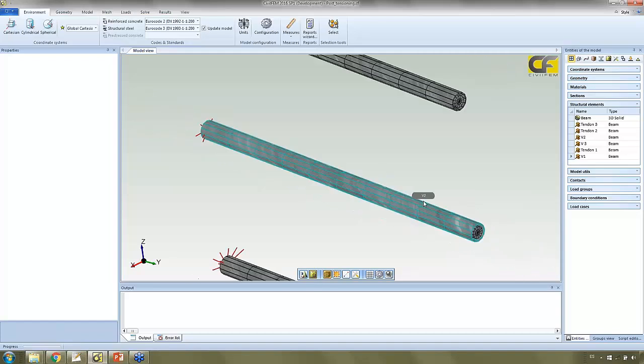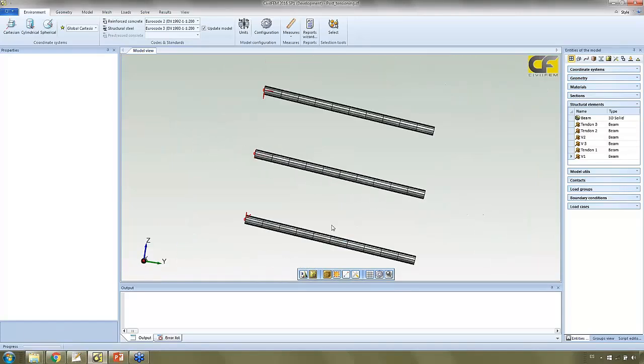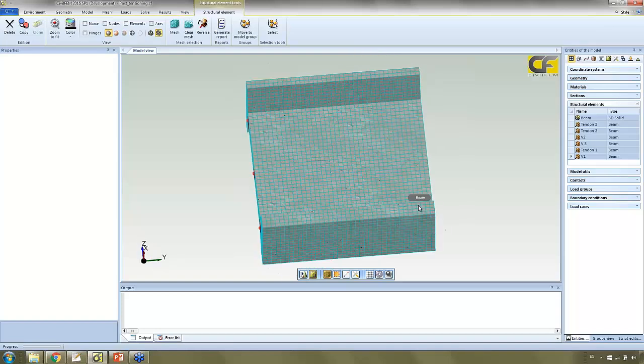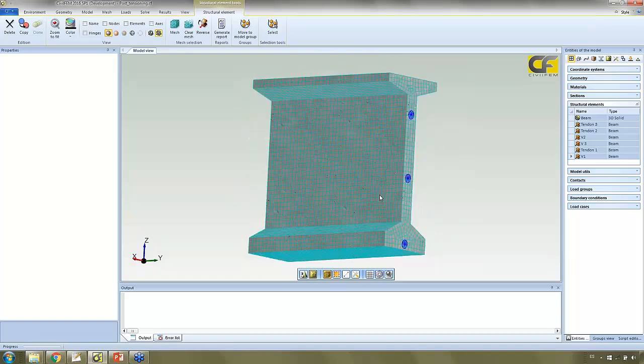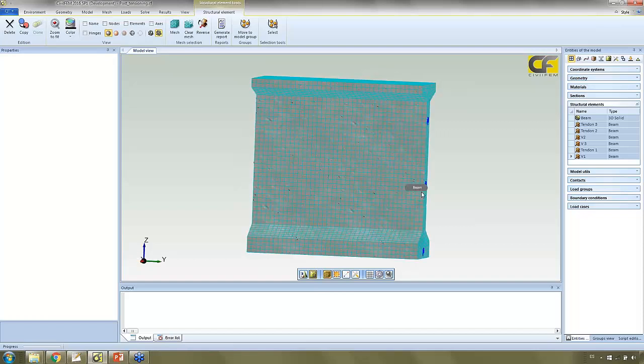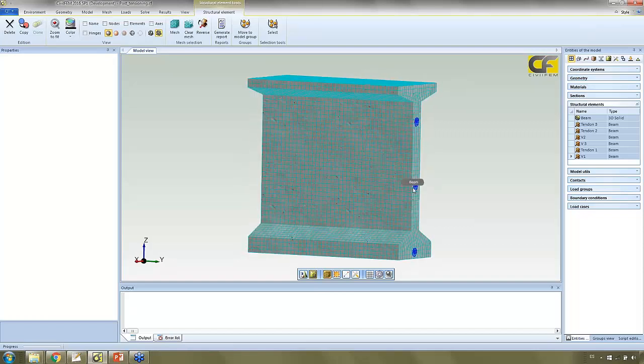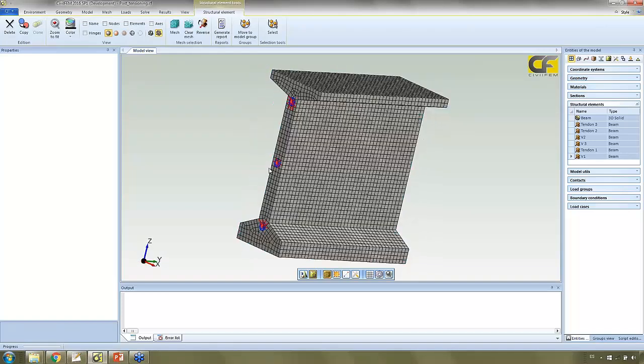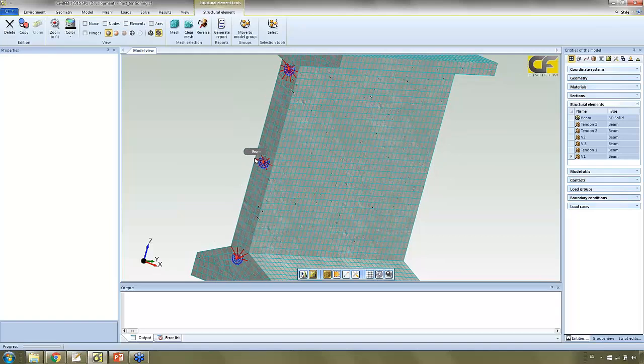What we've done is that for the cast, we have used the insertion option. So if we plot all together, we can see the mesh here also doesn't match, but we did the tubular section insertion inside the concrete. And then between the tendon and the cast we can have a slippage because it's not connected. We can use contact elements between them or coupling equations. We have used coupling equations in this case also for the compression.